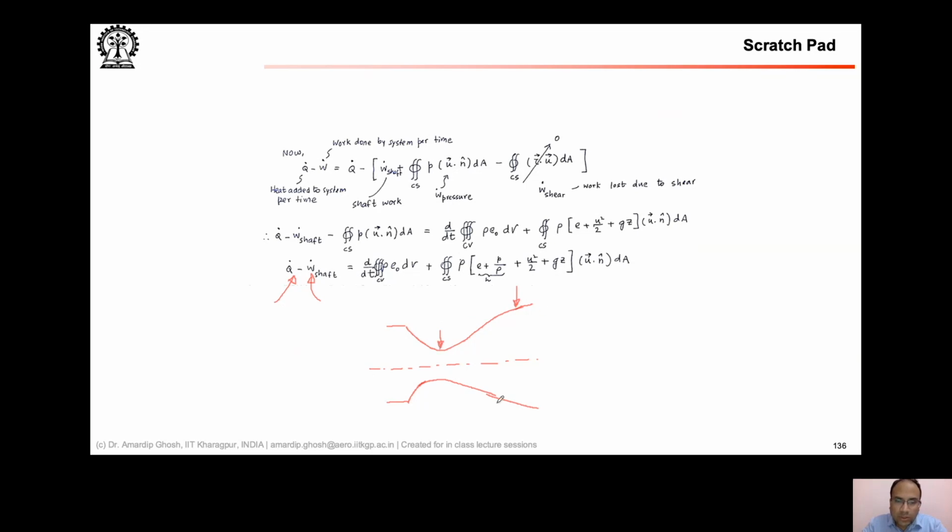The contour of these nozzles, you will learn something called the method of characteristics that allows you to create nozzle contours that lead to cancellation of shock waves, so that you get a clean flow field. So some of these things are there in compressible or high-speed flow problems. There is also the concept of choking. So if your pressure in the combustor is high enough, we'll talk about what is stagnation pressure, what is total pressure. You can think of it at this point as pressure inside a region where my flow velocity is 0.